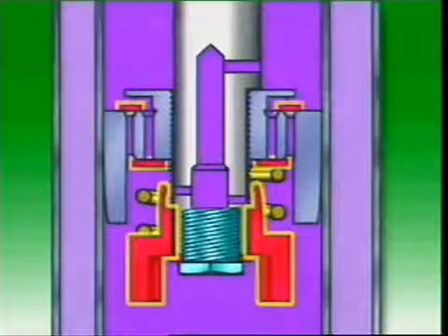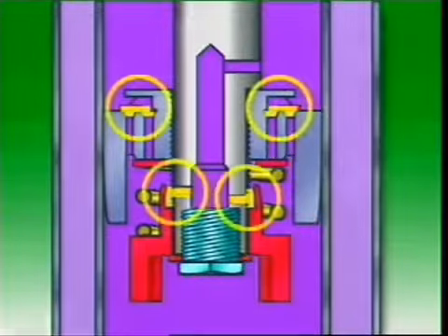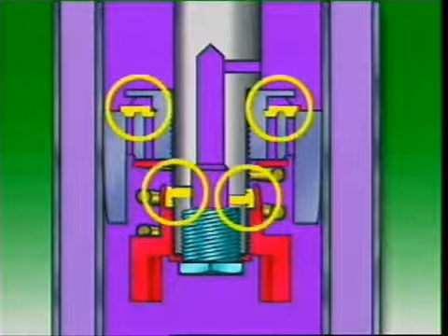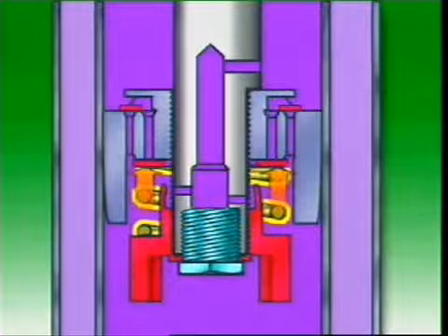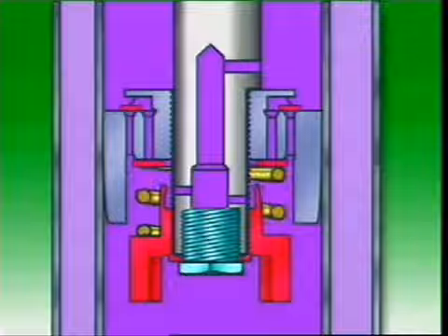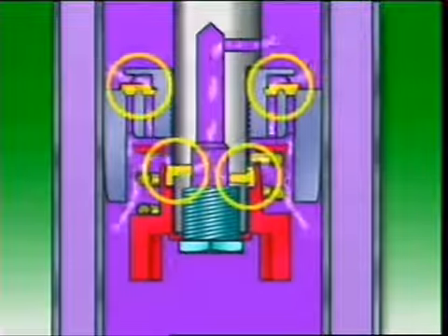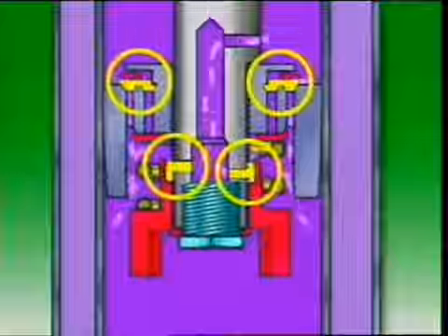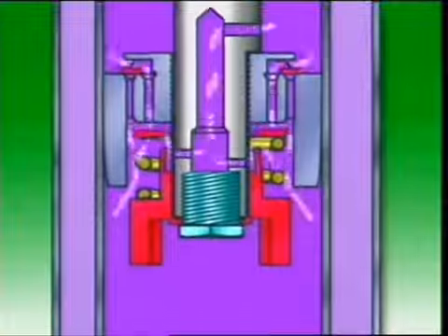The position of the valves in the piston can then be changed to vary the number of restrictions the oil has to pass through and to vary the force needed to open the valves. In this position, all of the orifices are open, and a small dampening effect is applied to the oil.